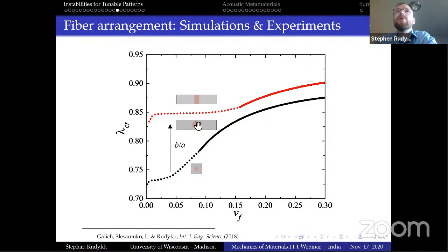Now one thing I will mention, not going into much detail, is the consideration of different distributions of the fibers in the cross section. Some interesting results that we obtained: it appears that the condition at which the instability develops is bounded by two cases. The first one is, of course, trivial. Basically, we limit that by this symmetric square arrangement. So that will be our lower bound here.